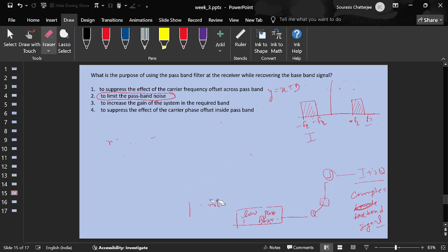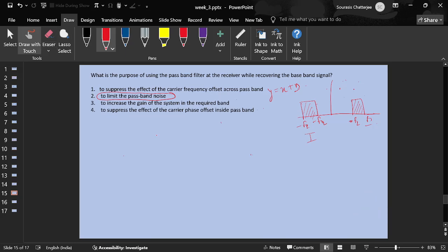So when you talk about noise, it's additive, white, Gaussian, right? There is a term white in it. So what does this white signify here? Power spectral density is constant. Power spectral density is constant and that is across all frequency, right? So it's like a constant line if I look at its frequency domain representation.